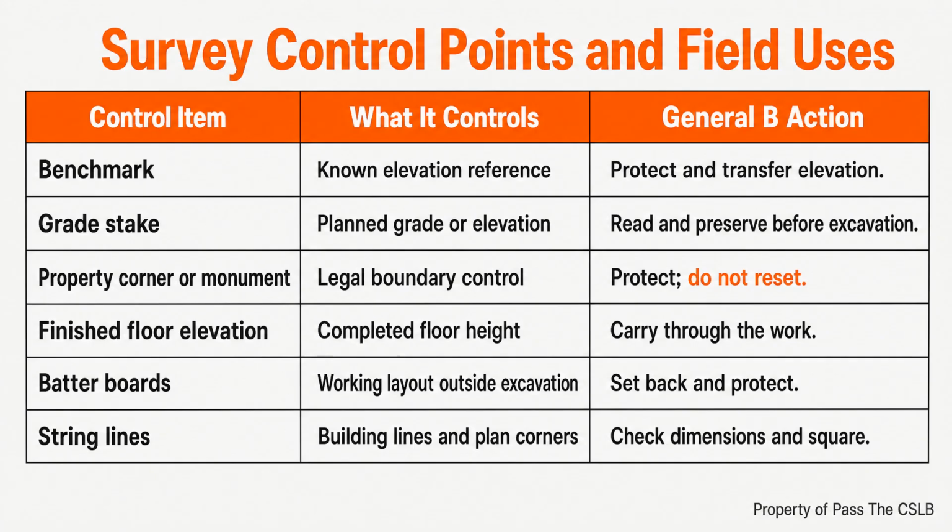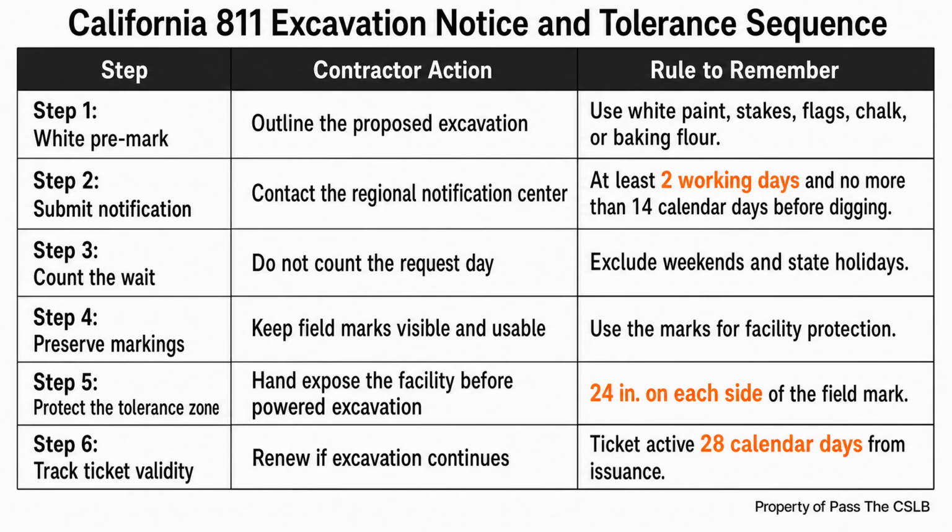Imagine the request is made on Friday before a Monday state holiday. Friday does not count. Saturday and Sunday do not count. Monday does not count. Tuesday is the first working day. Wednesday is the second. The earliest excavation day is Thursday.